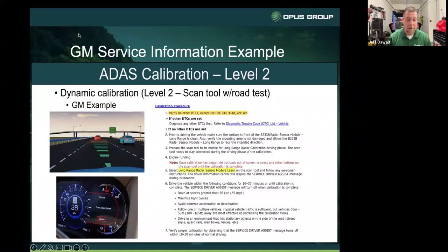15 minutes, it's calibrated. I got a shop down the street here in Vegas. We went out and did a windshield camera calibration. No sooner than we pulled out of the shop, going 45 miles an hour down this road, we were going about 50. The street was 3 lanes wide. We didn't get a mile and a half down the road and the car was calibrated and it was ready to go. So we just immediately flipped a U-turn and came back to the shop. So this information, again, is really good for just about any calibration that's out there. But again, always check your OE service information.